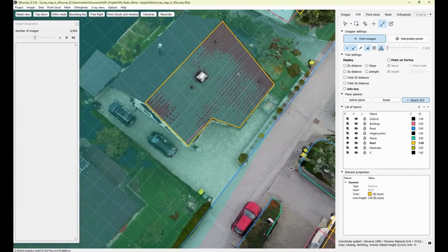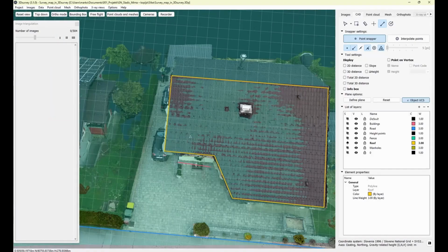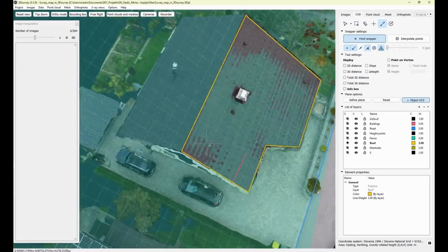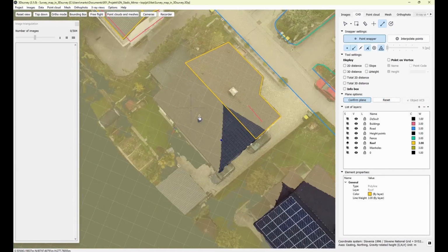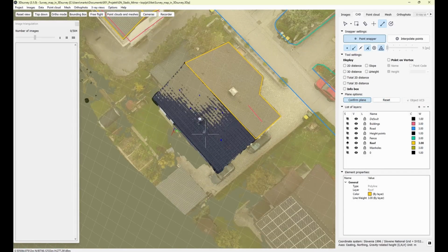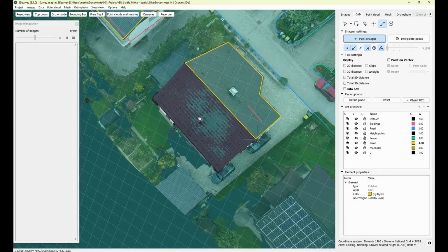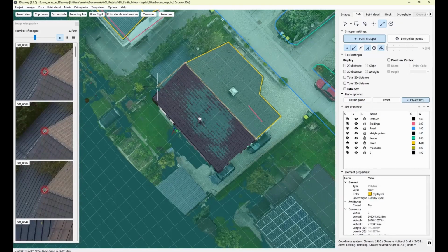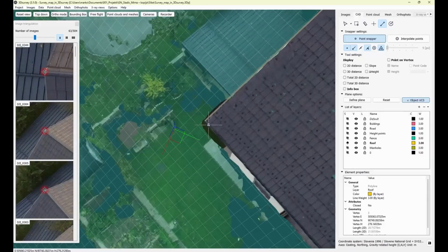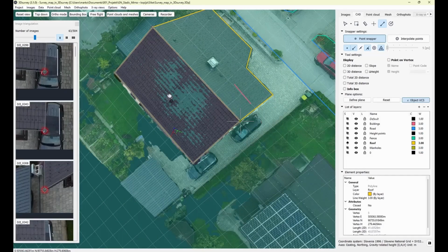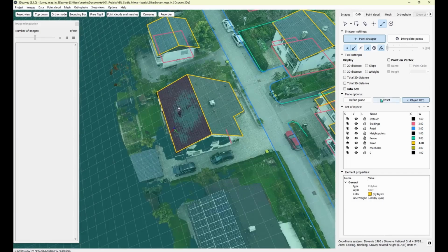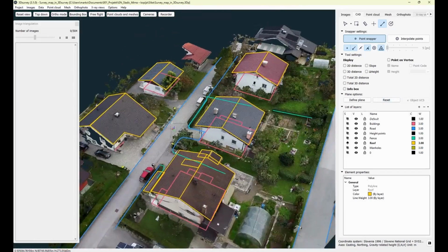Another trick with the Alt button to solve situations like that. Okay, and again reset plane, confirm, define plane, another one, confirm, main line, F8, activate the last snapper, check where we are, check the accuracy, that's it. Reset view and the last building is finished.